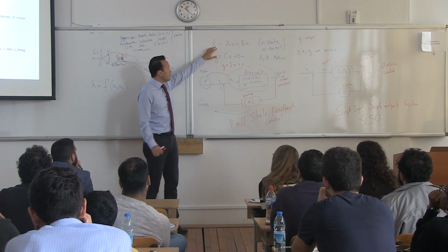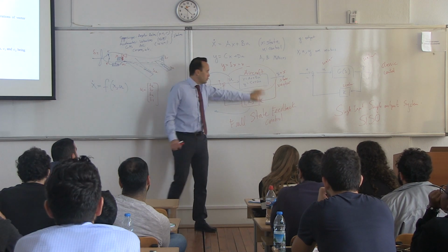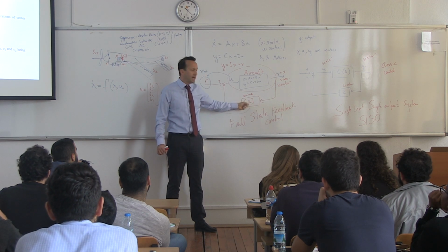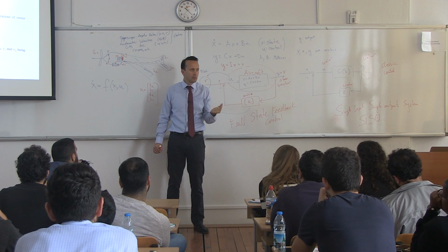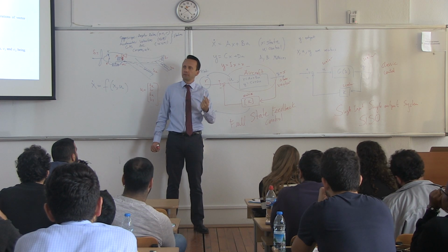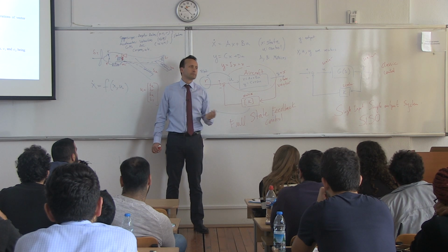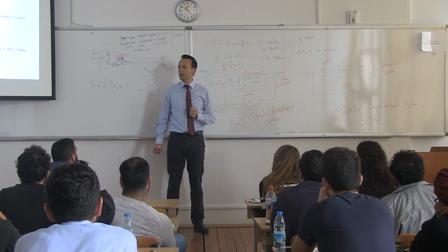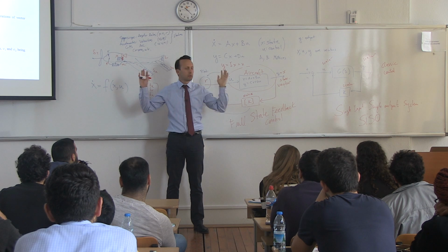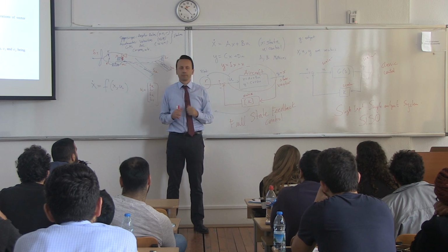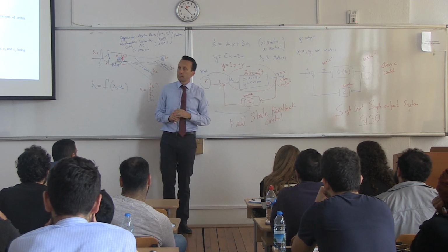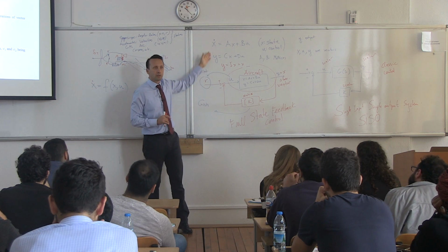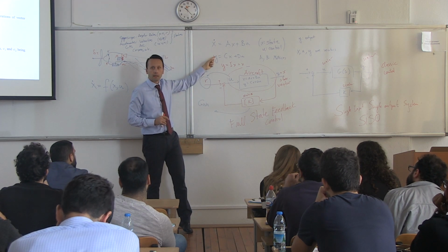So, therefore, when I use this in my controller design, I'm really designing a controller for only one equilibrium point, for one trim point. Let's say 30,000 feet, I don't know, 800 kilometers per hour, standard atmosphere, passenger airplane, whatever. For that flight condition, you can calculate this linear system, right?